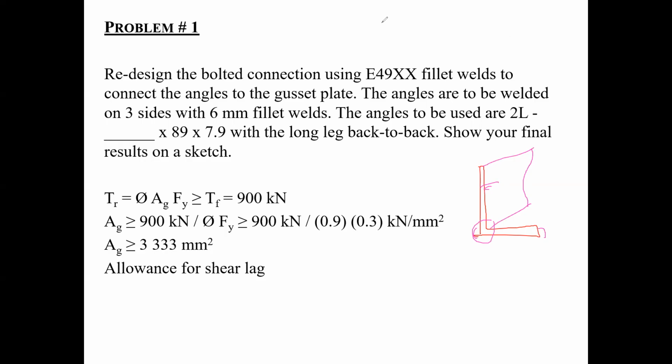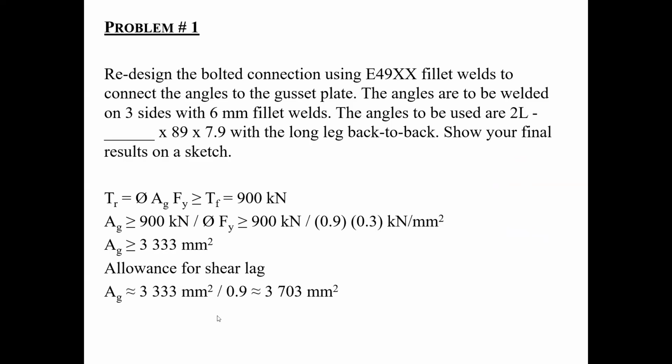Now, when it comes to welding, it's not as severe as when you're bolting. And therefore, I tend to increase it by 10% or 11% in this case, and this seems to be good. And if I've underestimated my shear lag value, that's just a question of going back and doing another iteration. But this is a good starting point. And like I said, this is a guesstimate. There's nothing in the books that tells me that I need to start with 0.9. I could have used 0.7 and I would have been that much more conservative. But this is a good guesstimate for shear lag for welding.